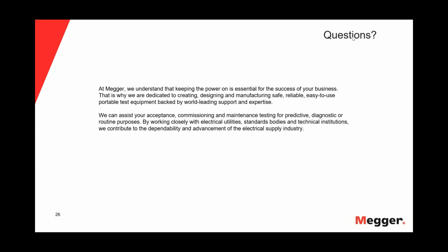Now, the VLF test is a totally different test. The VLF test is a withstand test, and it can find out if the insulation is compromised in terms of its, let's say, insulation resistance. So if you have a low insulation resistance, that means if you go to the test voltage, you get leakage current. The higher the leakage current, eventually the leakage current will lead to failure, right? So that's one of the ways that a cable can fail under VLF.